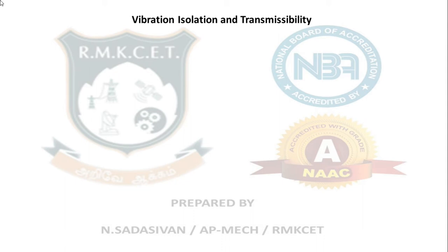Now, why do I tell you all these things? Imagine how much vibration comes in. You are having one of the best machines in the world, a very good German manufactured machine, but if you are unable to tap out all the vibration out of the machine, what will happen? Even though your machine is very good, if you have not properly balanced the machine and kept it on the foundation, all the vibration and the chattering disturbances that shake your machine will be directly reflected on the surface roughness of your job.